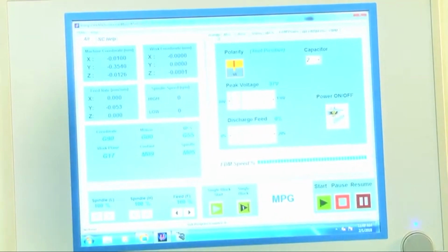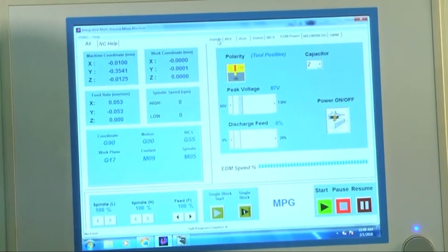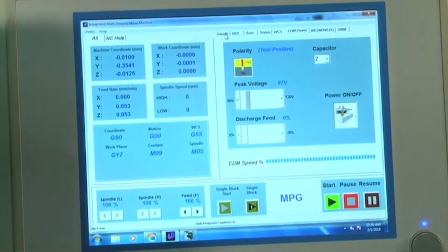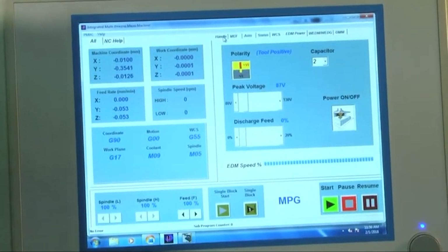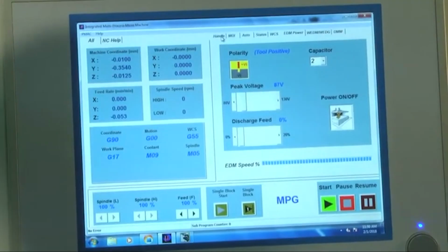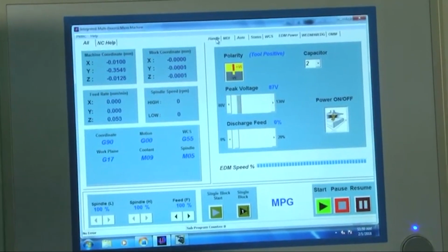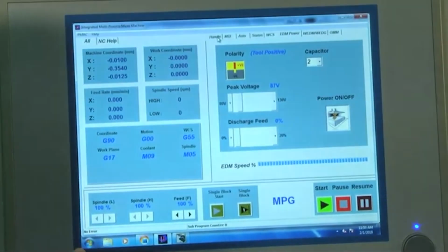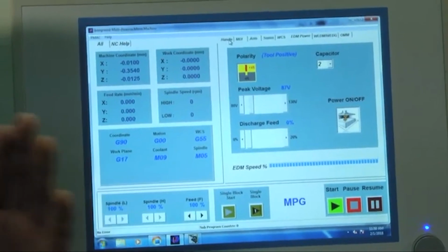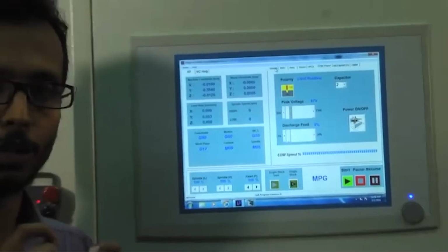select a blank for the micro end mill tool. So starting with, what we are doing here is we are selecting a blank as a commercially available 0.5 mm or 500 micron end mill tool. On the surface of that, we are flattening the surface on the top to remove all the available features, and over that we are making our own end mill cutting tool, that's the micro end mill tool.